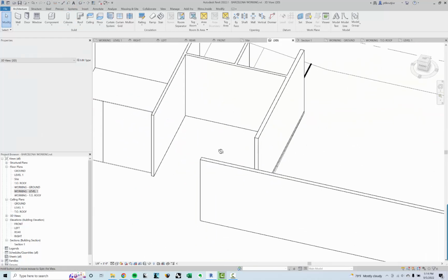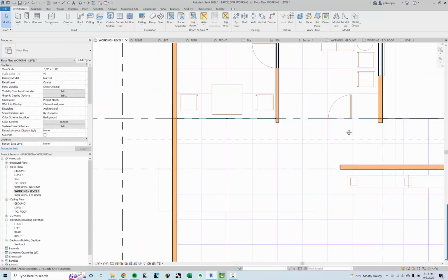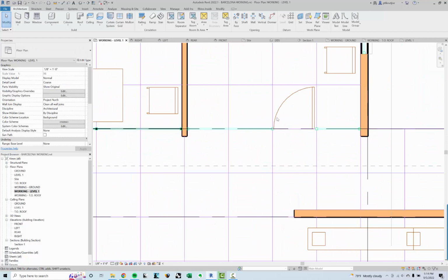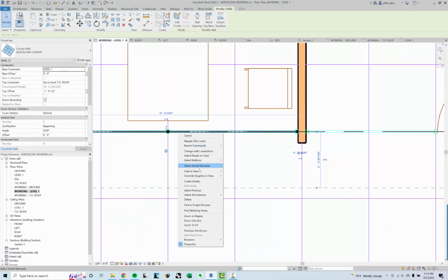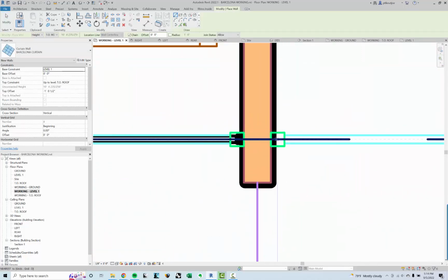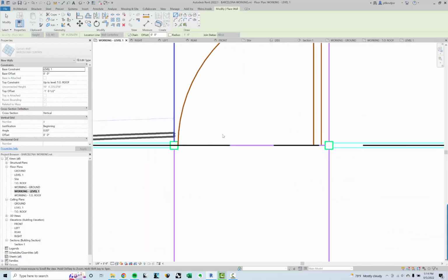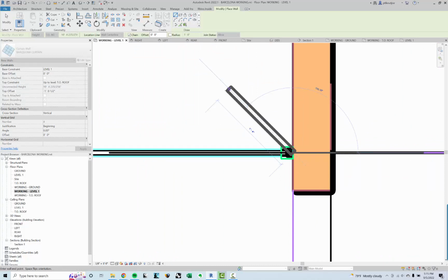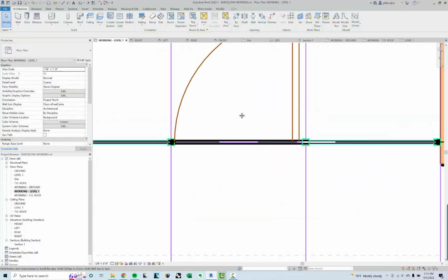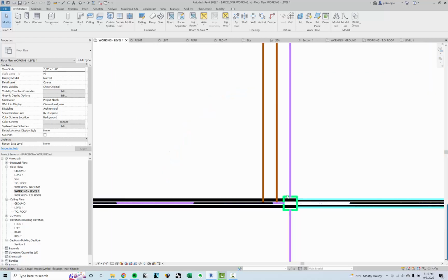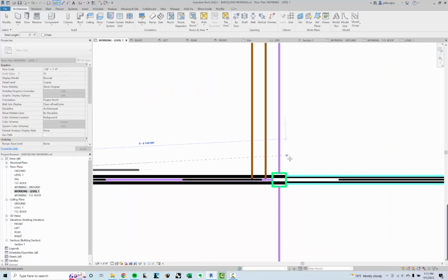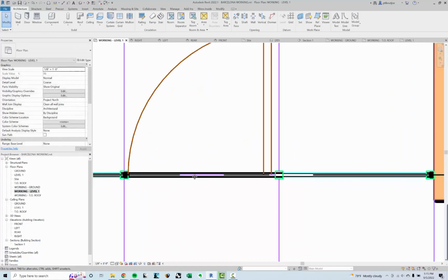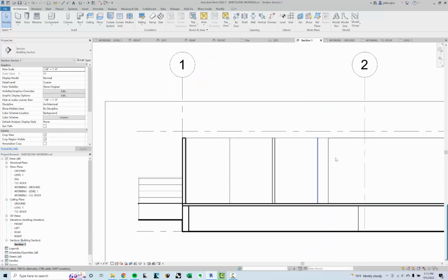Okay, so I'm going to do one more curtain wall here so you guys can see how to add doors. So I'm going to right click on this, and I can actually go to create similar. This is another good trick, which just allows me to create obviously the same thing as I did before. Now I've got that. My mullion spacing looks pretty good, but I need to get a door in there. So what I'm going to do is this door, let's see what that dimension is. This dimension here is, let's call it 3'6" for the purposes of what we're doing today.